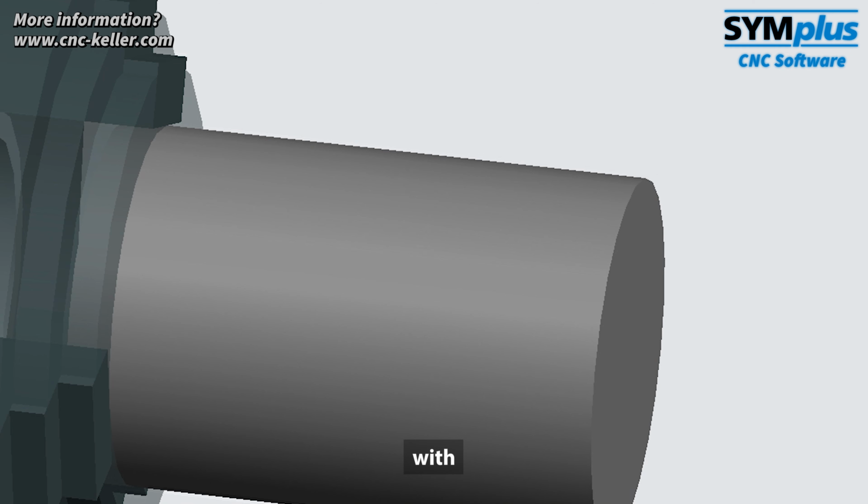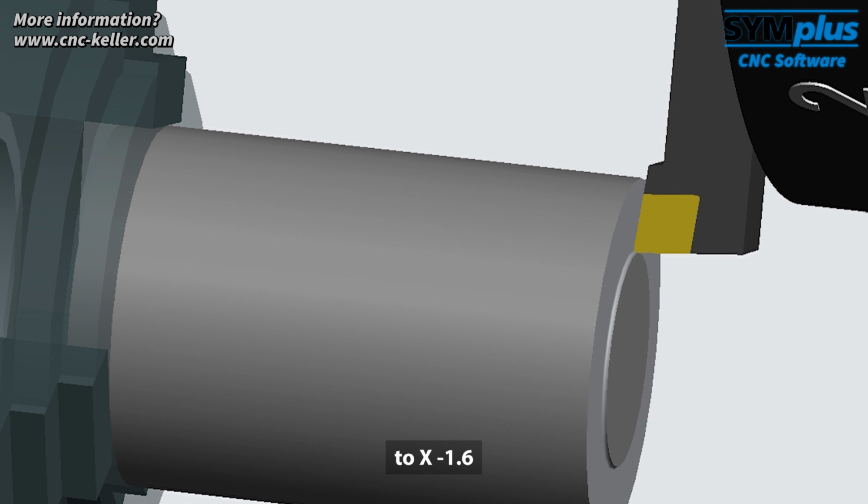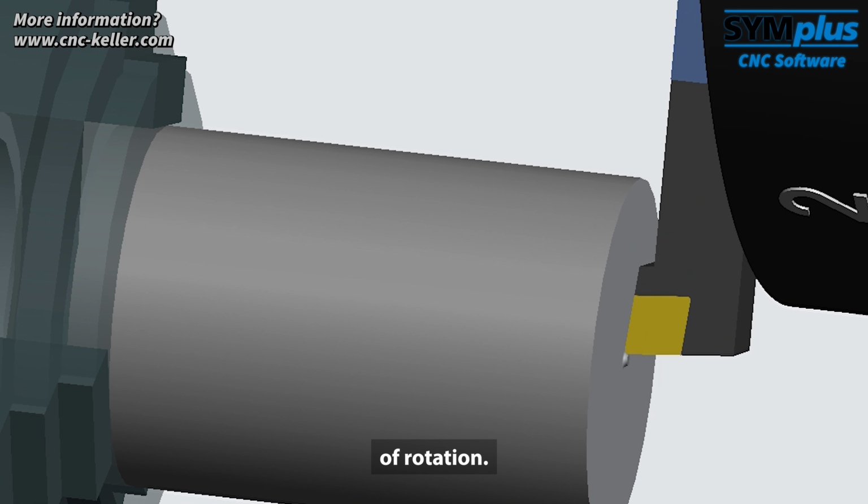The machining starts with longitudinal turning. Using G1, the blank is faced to X minus 1.6 across the center of rotation.